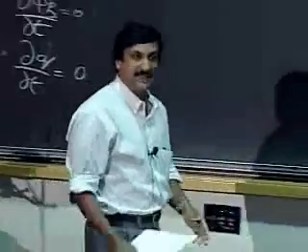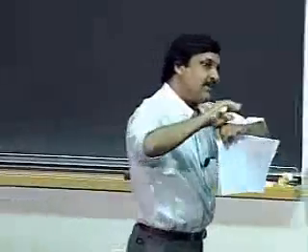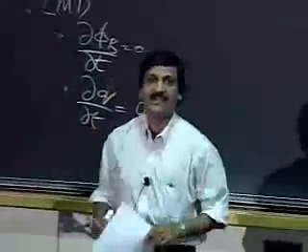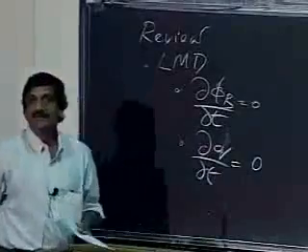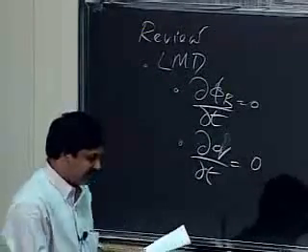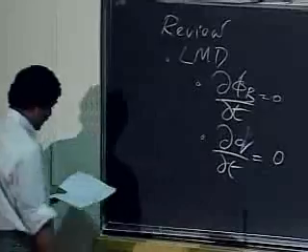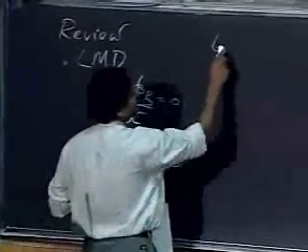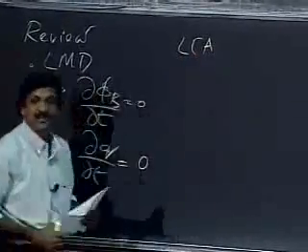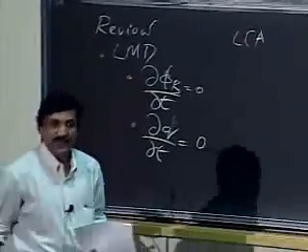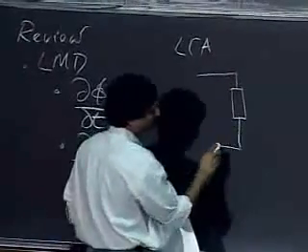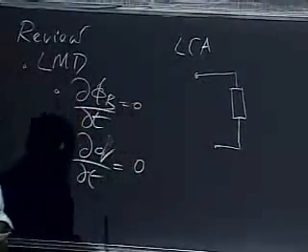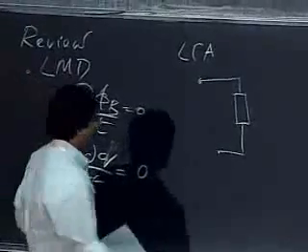We will see examples where if you choose some piece of an element, there might be charge buildup, but if I put a box around the entire element, I'm going to assume that the rate of change of charge is going to be 0. So what this did was it enabled us to create the lumped circuit abstraction, where I could take some element of this sort. This could be a resistor, a voltage source, or whatever.